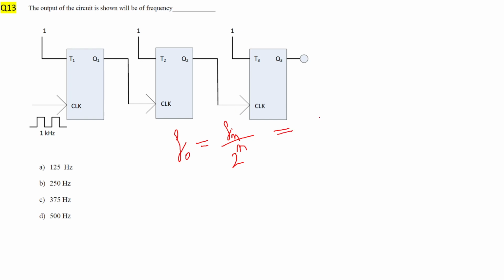So how many flip-flops are there? 3. So F in divided by 2 raised to power 3, that is F in by 8.